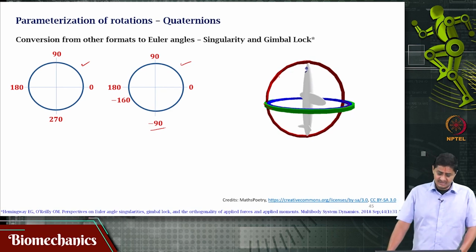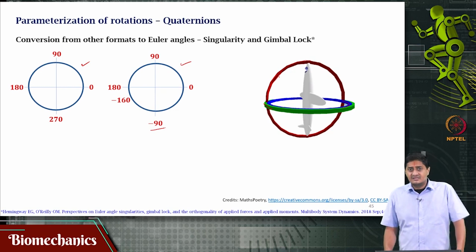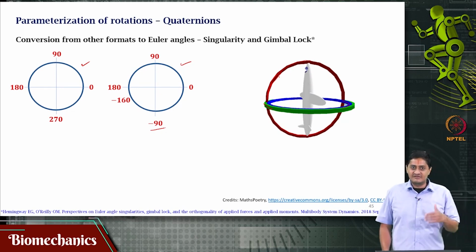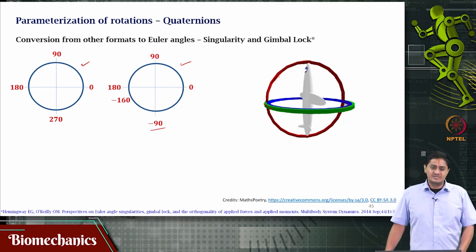It should be oriented such that the axis that is likely to go into lock position, or the axis in the middle, almost never goes to 90 degrees or approaches that 90 degrees. Even as it is approaching, the problem becomes severe. So, 88, 87. So, it does not have to be exactly 90. From about 75, 80 onwards, the problem begins to build up.